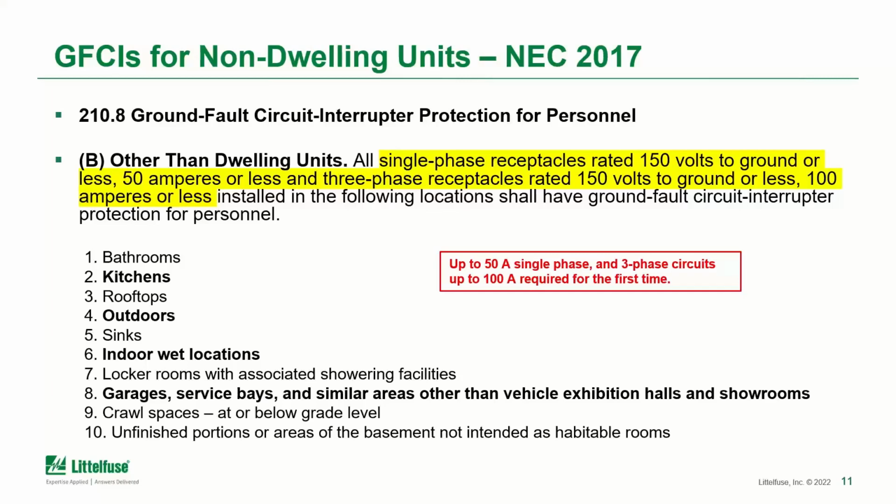code. And this is really recognizing the fact that shock hazards are not limited to those 125 volt, 20 amp circuits. So the three-phase receptacles, higher amperages, they certainly pose similar shock hazards. And as three-phase voltages and higher amperage circuits mostly exist in non-residential applications, that's why the non-dwelling unit section of the code is what is being updated with some of this information. So what I'm highlighting here is just a couple of recent changes to show this advancement.